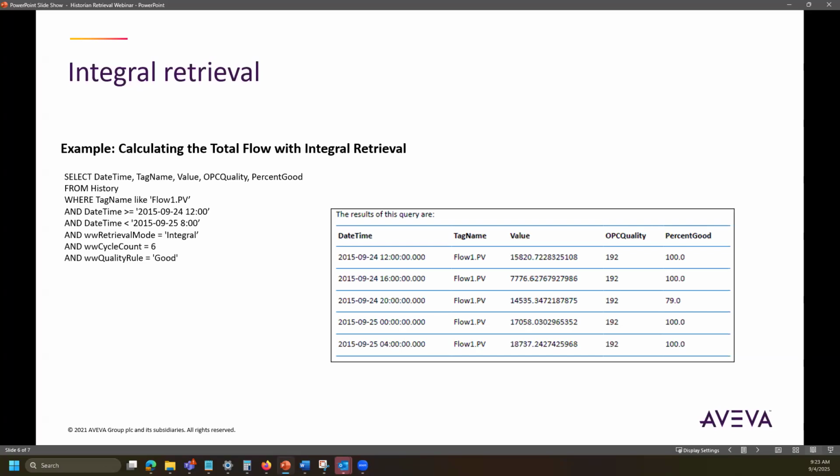or after the area has been found, it is scaled using the value of the integral divisor column in the engineering unit table, right? So this divisor expresses the conversion factor from the actual rate to 1 unit or to 1 of units per second. So for example, if the time weight average for a tag during a 1 minute cycle is 3.5 liters, and we're going to see an example like this now in the query tool.